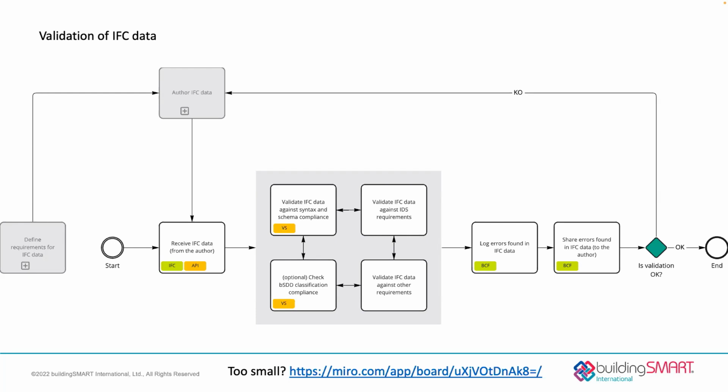Yeah, so we have a different policy on MVDs. In the past, MVDs were basically separate standards that weren't necessarily interoperable with each other. As this example currently, for example, on IFC for precast, which has a geometry type that is not available in the reference view. So we have an MVD policy currently that says we have 3 base MVDs, 3 implementation levels of IFC: reference view, alignment-based reference view, and transfer view. And we expect vendors to implement those levels, as many as they want. And those will be checked in the validation service as well. So if you see MVDs as kind of performance levels of IFC, we have 3. Those will be included in software certifications.